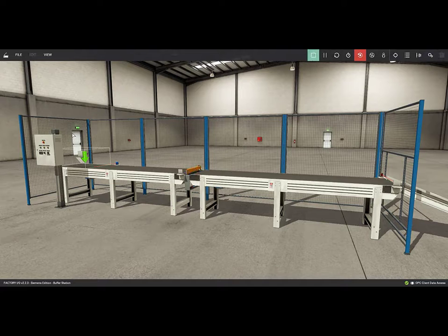Now we start the simulation. When the operator presses start, the boxes begin to appear. The buffer conveyor actuator is activated, and the boxes move until they meet the stop blade that prevents them from continuing to advance. Then the stop blade is deactivated. The first conveyor is activated and passes a box to the second conveyor. The box that comes behind is detected by the at buffer exit sensor, activating the stop blade.